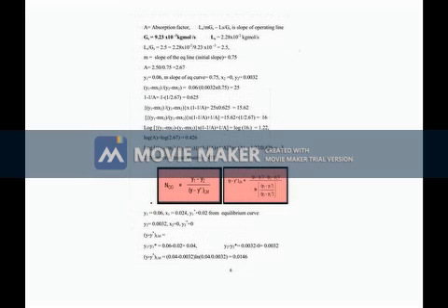The molecular weight of air is 29 and of ammonia is 17. If you find the average, it will be 28.28. Or if you don't want to do it, since the ammonia is only 6%, instead of taking the average molecular weight, you can take the molecular weight of air, which is 29. To be accurate, you have to use the average, that is 28.28.